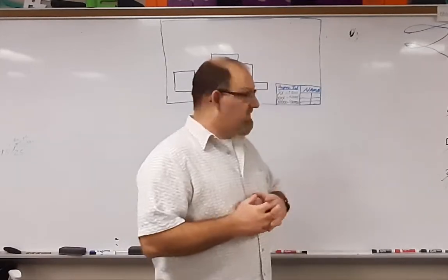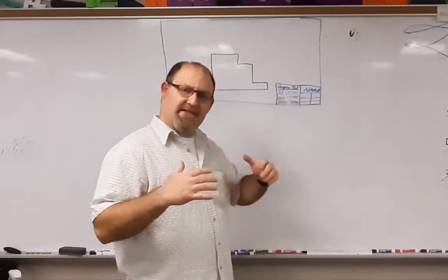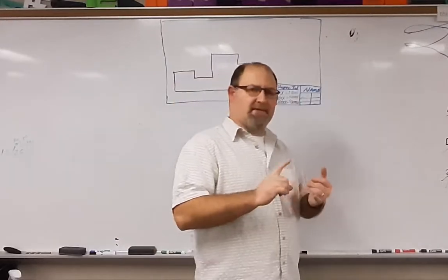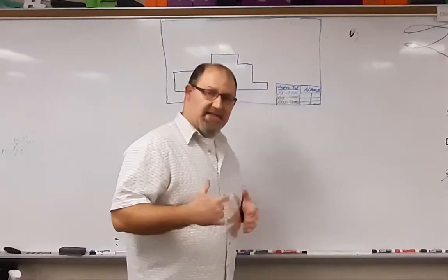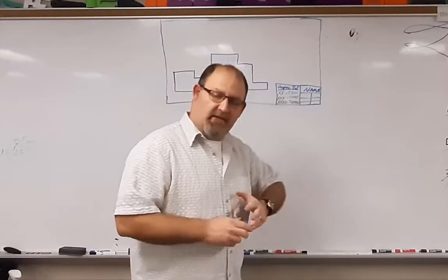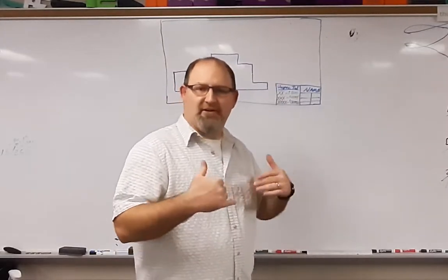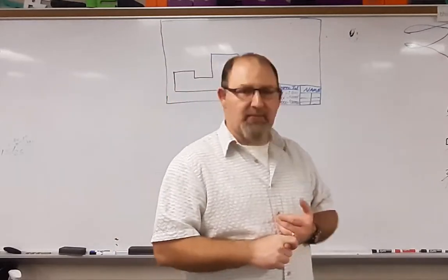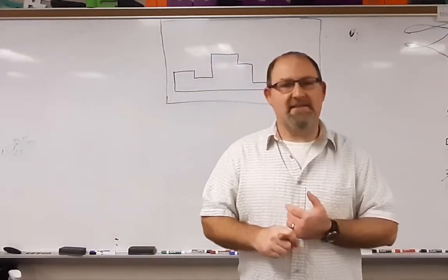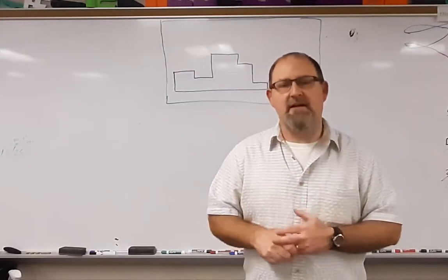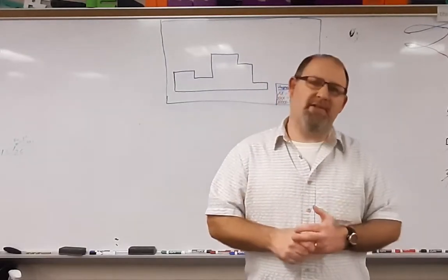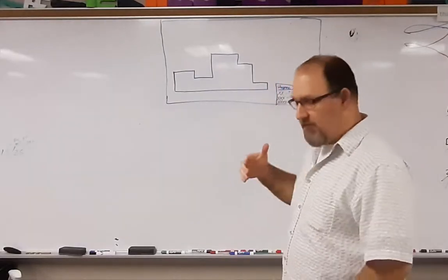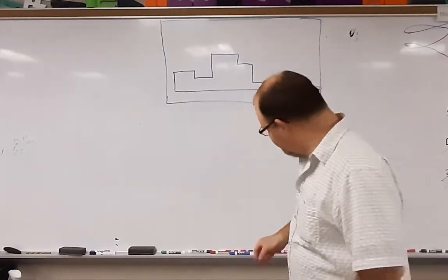So we've talked previously about unspecified tolerances and how they interact with parts. We've talked about concepts like MMC and LMC. In this particular video, we're going to be looking at accumulated tolerances. Specifically, we're going to be tying this in with dimensioning. We're going to be looking at some different styles of dimensioning: chain dimensioning, broken chain dimensioning, and a datum dimensioning method. So we're going to be going through those as we talk about this here.